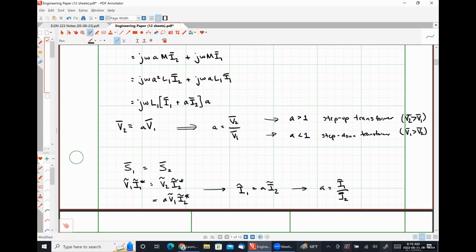If we step the voltage up, we should have to step the current down in order to keep the power constant. Right? So any step up voltage transformer is actually a step down current transformer and vice versa. That's also another one of the reasons why we choose to use transformers and transmit power at extremely high voltages over long distances. The higher that we can get that voltage to be, the smaller the amount of current has to flow along the wire, which means we can use smaller wires, which are cheaper. And it also means that less losses are going to occur due to the wires heating up because they're carrying less current. Right? So our I squared R, or our copper losses, will be smaller the higher we can get our voltages in a distribution system.